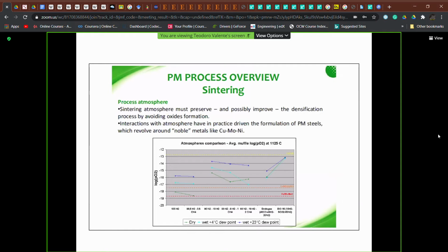And so we can have a situation in which, as well as in the gas atomization, we need to carry out our sintering step in protective or inert atmospheres in order to avoid that oxygen, for example, can react with iron, or could react with titanium, or could react with aluminium or with nickel.